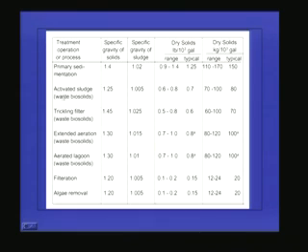For activated sludge, whatever is coming from the secondary sedimentation tank waste, the specific gravity of the solids is around 1.25 and the specific gravity of the sludge is only 1.005. The trickling filter has a better solids specific gravity of 1.45, but the sludge specific gravity is only 1.025. For extended aeration it is 1.3 and 1.015, because extended aeration sludge is mostly inorganic in nature, since the organic matter or biomass present in the system gets auto oxidized during the aeration process.